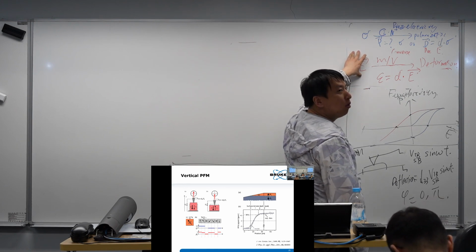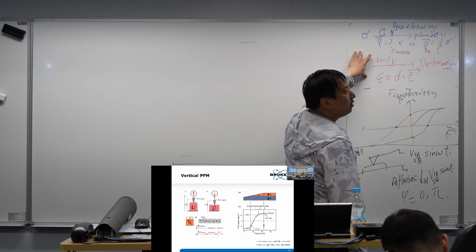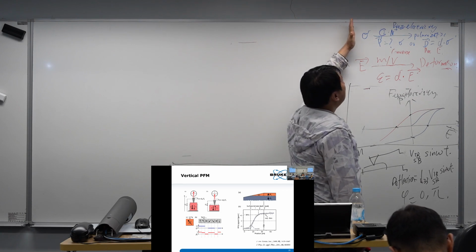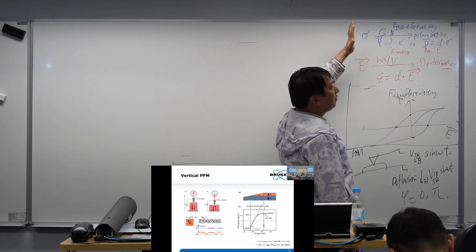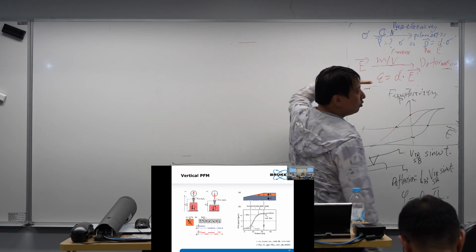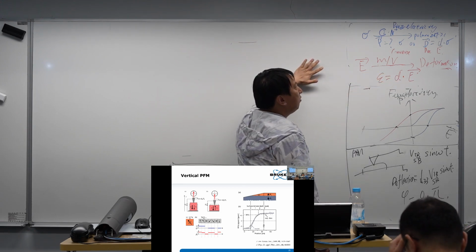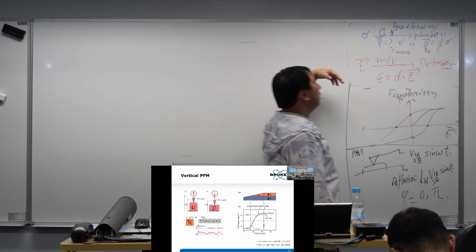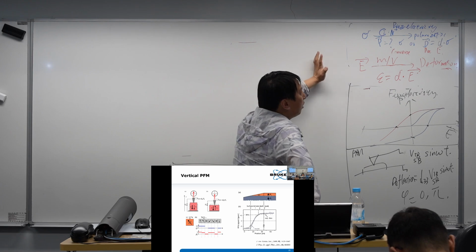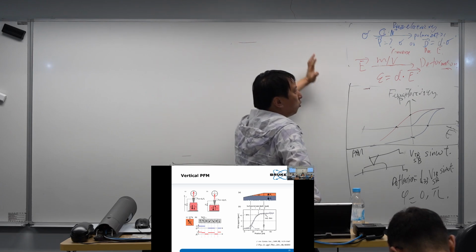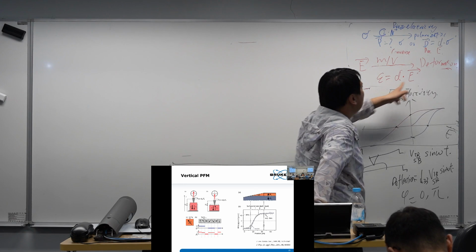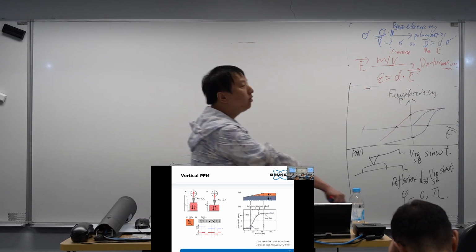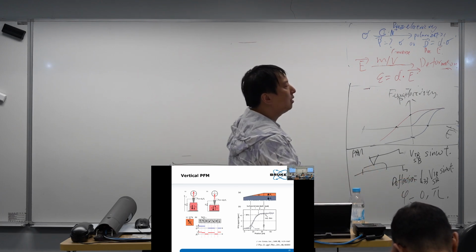And one important component is the d33, which represents that we apply a force in the z direction, perpendicular to the z-direction area, and we get the polarization in the z direction. Or we apply an electric field in the z direction, and we cause a deformation in the z direction. That's the d33. And the piezoelectricity depends on the symmetry.